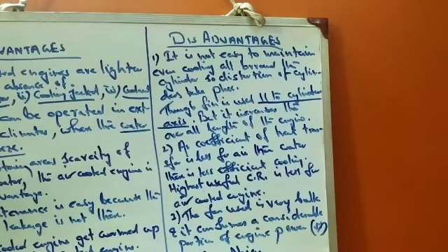The equal distribution of heat will take place if you use fins parallel to the cylinder surface. But if you use more cylinders, the overall length of the engine will increase. If you go to 4 cylinders, 5 cylinders, the overall length of the engine will increase.